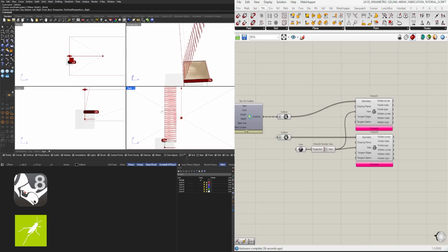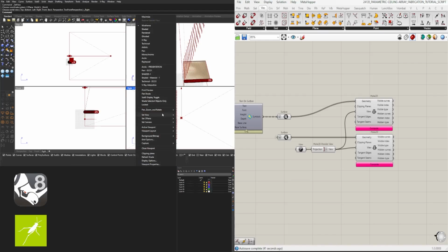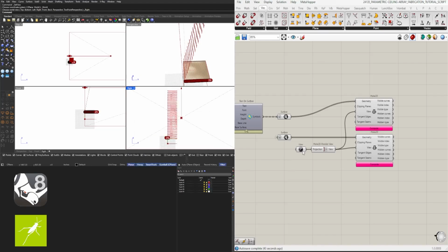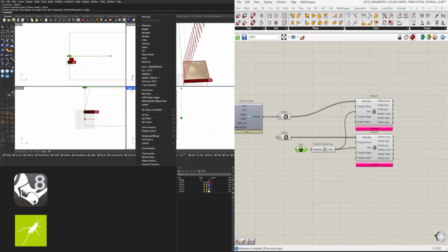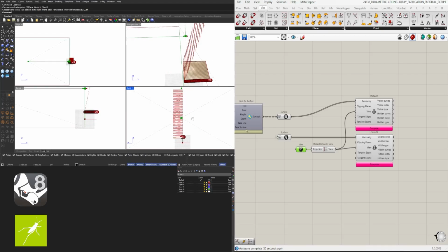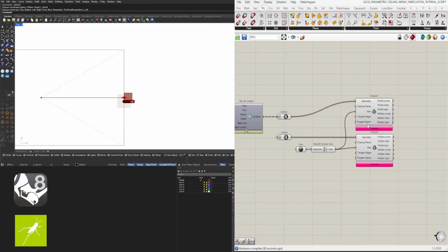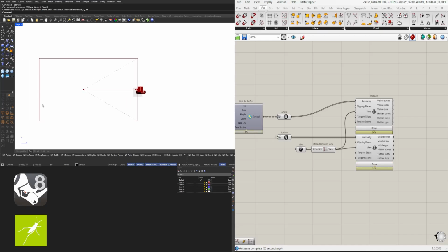So what I'll be doing here is showing you the thing that I did to fix that. I'll change this view, which the views in here that are contained in this component are going to be the views that you have on your viewport. So I'll go to set view to left, center this here. But notice now that when we do make 2D like this, it's not going to work because it's not intersecting with this view.